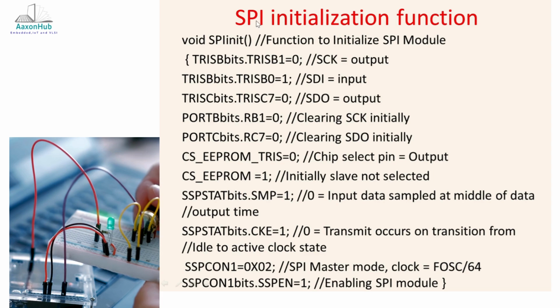If this SPI is initialized, let's say you have connected a PIC18 microcontroller with a peripheral device such as an EEPROM. Now the EEPROM itself has some kind of commands to get initialized. So in order to do that, we need to enable that respective EEPROM IC. Through that you will be able to transfer the data from the PIC18 microcontroller to that EEPROM IC.